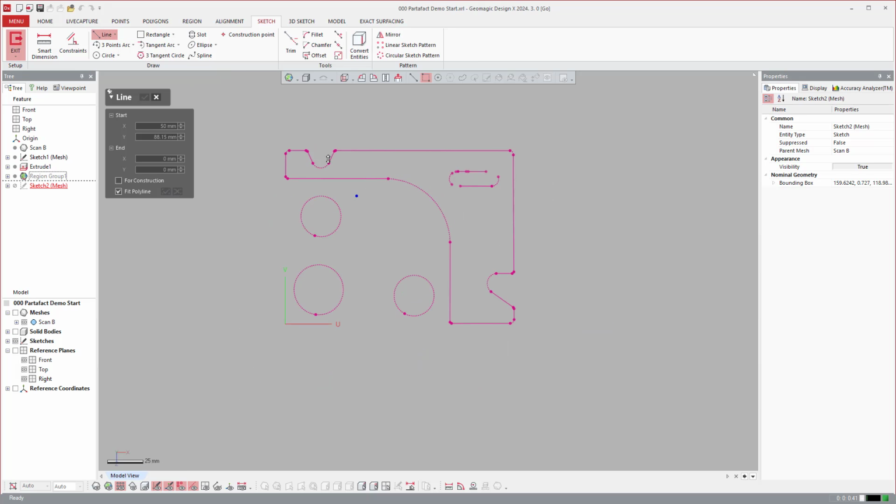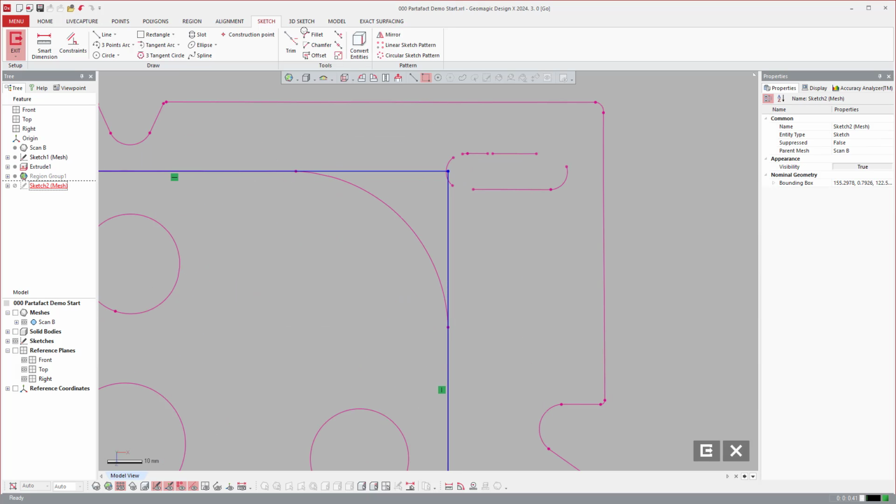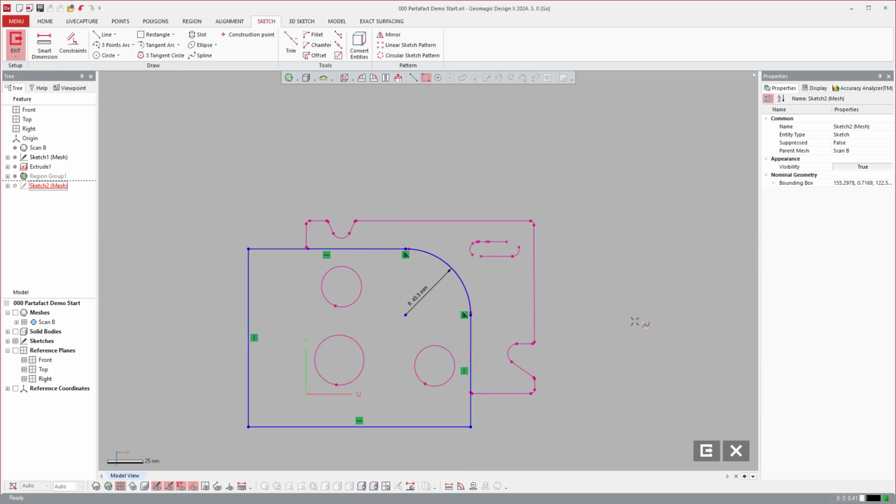If I were going to draw this, one way to do this would be to come in like this and just draw it out. And if I wanted to snap it in this instance, I can snap it. I can fit lines individually if I want to, a whole host of different ways of doing it. I can also drag and then determine what I want this radius to be. If I go ahead and accept it, I can say, hey, maybe this needs to be 45.5, hit OK, and it will override and dimension that for me.